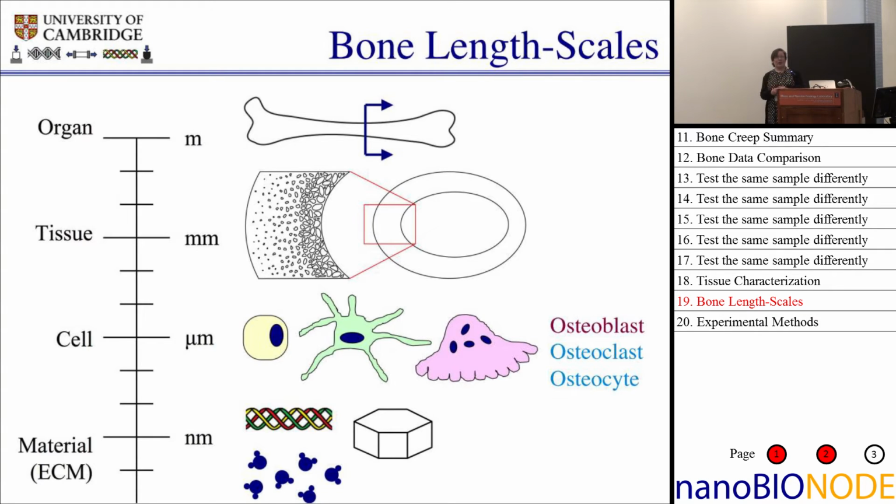Like in a bend test, you have this complicated geometry, you've got this complicated porosity distribution, and so being able to go in with nanoindentation and test the solid material and try and really look for material property differences is probably one of the reasons that there have been so very many nanoindentation studies done on bone, although mostly on dry bone with a Berkovich indenter, with Oliver-Pharr data analysis. So it may be sort of hard to interpret them.